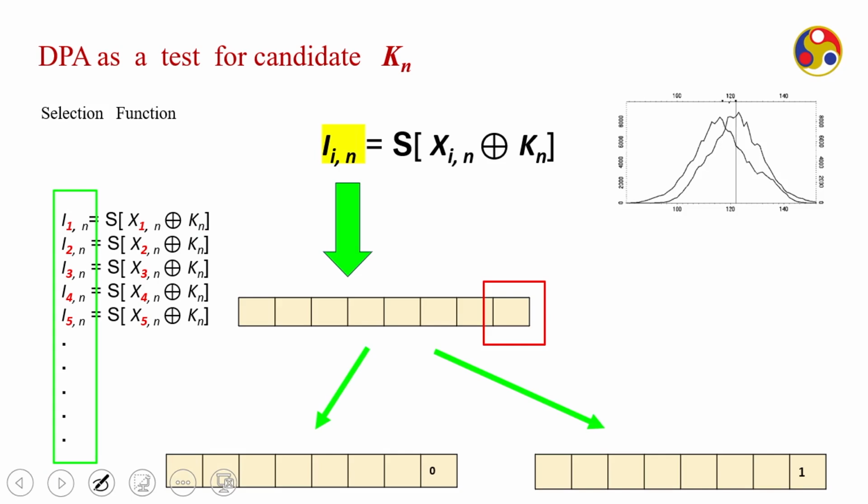This is exactly what I am going to do. I will run it, and I will focus on the LSB, distribute the traces into 2 sets, whether it is 0 or 1, get the 2 power patterns, and see whether they follow what I identified earlier. If I can see that this is for 0 and this is for 1, say LSB equal to 0 or 1, and they are distinguishable, then this is the key.